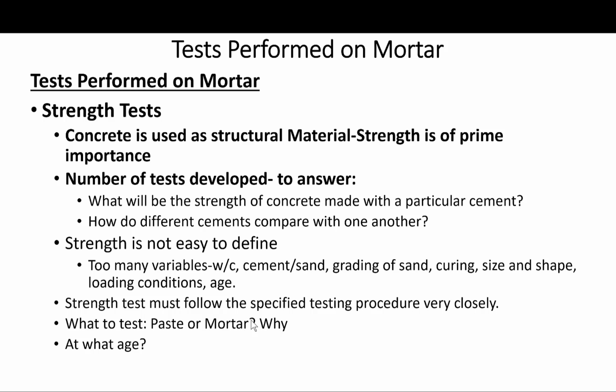So you could please refer to that and see what the strength requirements are by ASTM. And again, when you are conducting a compressive strength test, usually you draw a curve of strength versus age or time. One thing to remember about that: the shape of the strength-time relationship is important, not simply the strength at any single point. So the shape of the curve is important.